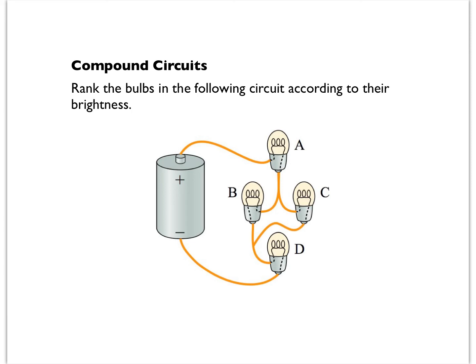They're connected together here, and they're connected together here. So the potential difference across bulb B is going to be the same as the potential difference across bulb C. Since the current in the bulbs is delta V over R, the same potential difference across them is going to give the same current. So I'm predicting bulbs B and C will have the same brightness.